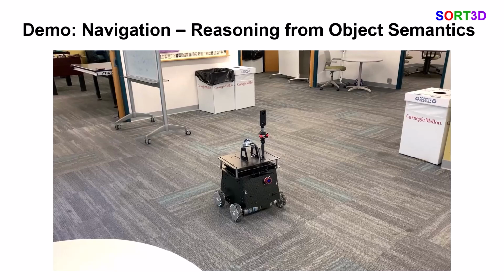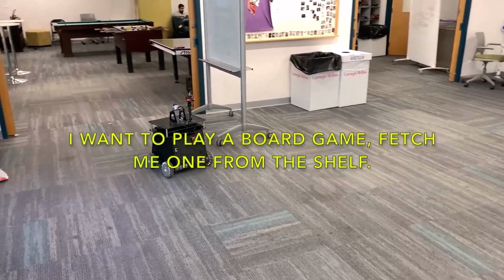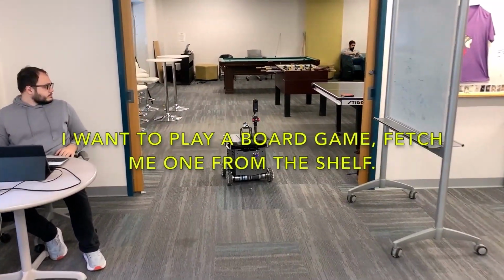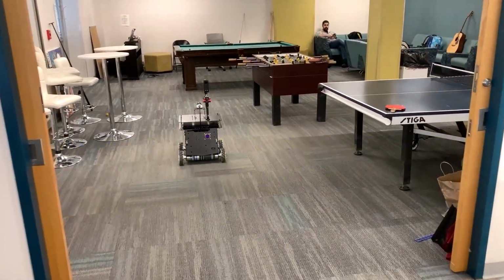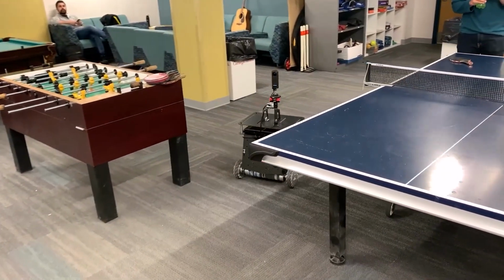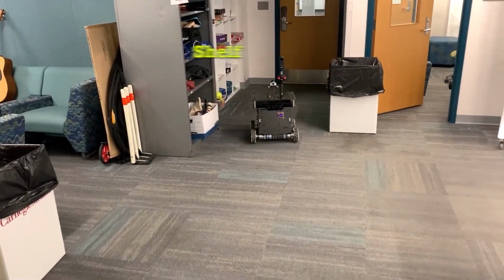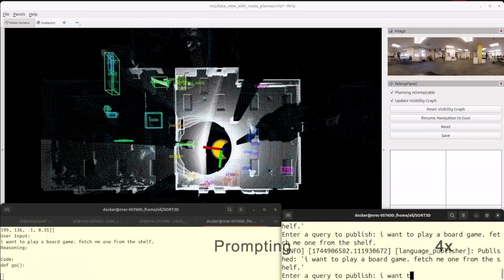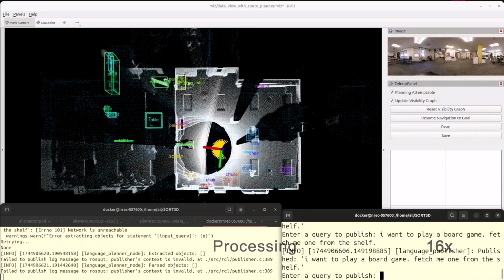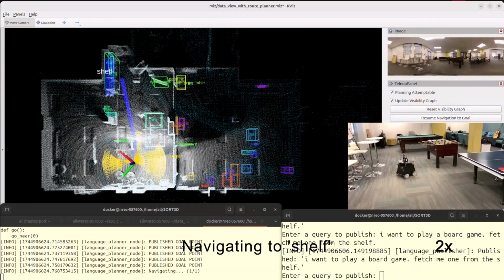Finally, we demonstrate the role of our captioning module in allowing the system to reason about an object through its semantic attributes. In this scenario, we task the robot with fetching a board game from the shelf. Here, SORT3D goes through multiple steps of deduction. It first reasons that it must choose the correct shelf, which is the one that has board games on it. The LLM uses the object captions to determine the shelf described as having colored boxes on it, deduces that they are most likely to be board games, and chooses that particular shelf, demonstrating the interplay between semantic descriptions and LLM reasoning.